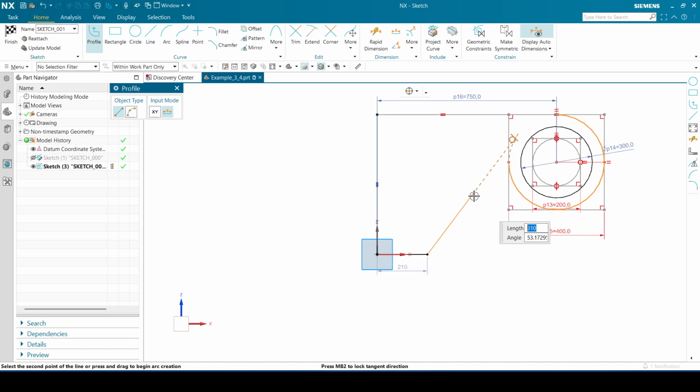and you'll see the note now that this constraint suggestion pops up. In the note in the sketch, it says the diagonal 130 millimeter line is tangent to the 200 millimeter radius circle. So what it's suggesting at the moment is what we actually want. So we can just click that, we're happy with that, then this goes up, here's vertically, and now we want the arc to go this way, and we want it to connect to that point. You can just click, yes, connect to that midpoint, and then close that.